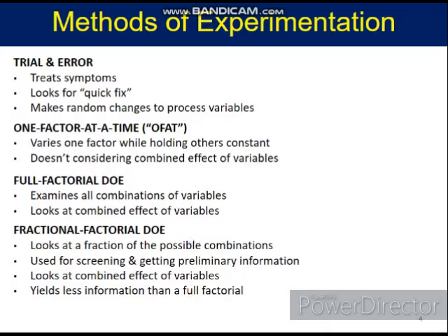You assess the impact of seven parameters, and then you get the data that tells you the top, let's say, four significant parameters. You choose those four and run a full factorial design experiment. Then you can have all the information with regards to the effect of each variable on the output response and also the combined effect of the variables on the output response.